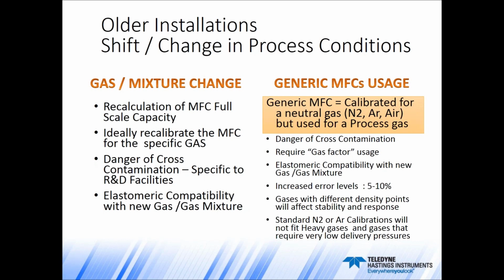I would like to point out the danger of cross-contamination. And again, this is specific to R&D facilities where a specific system or bench is used to run a set of experiments, and then the same type of flow controllers, the same flow controllers, are being used with a new gas. The danger here comes from running two different types of gases that are not compatible with each other and can generate a chemical reaction if there's traces of the previous gas in the flow controller.